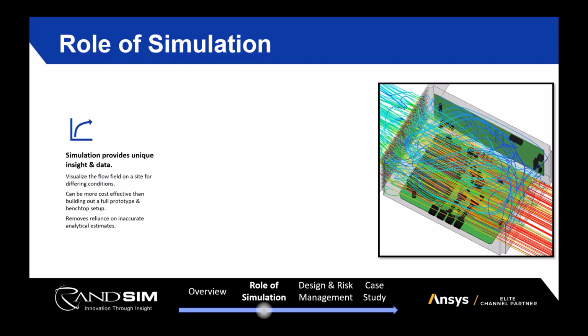You can, for example, with fluid flow, you can visualize where that fluid is moving, and you can see that in an image on the right to see how much fluid might be circumventing your heatsink, right? The heatsink's goal is to extract thermal energy from a component and dissipate it to the air streams. But if most of your air is moving around that heatsink because there's too much of a pressure resistance for air to move through the heatsink itself and extract that energy, it's not going to be operating as efficiently. And when you do physical testing, it's not always as easy to visualize some of those things. Yes, you can do smoke testing, but sometimes it's a lot more difficult. It requires a lot more care in those experimental setups than running analyses, which can really give you a lot of that extra insight.